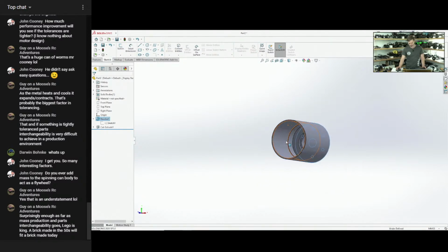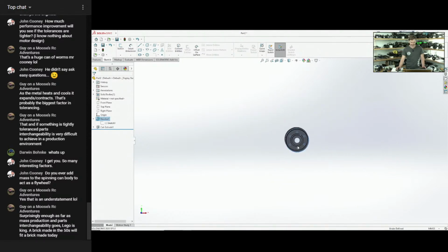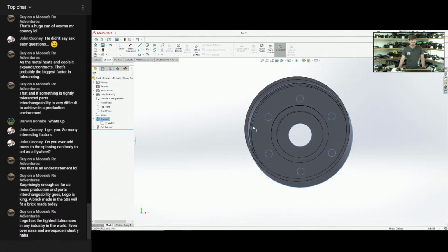So what we need to do is, it's a balancing of tolerances on so many levels. If the stator ends up sitting kind of crooked off to one side, like let's say we did just 5/1000ths of an inch tolerance on there, and it's like a hot dog in a hallway, then our stator, when we glue it in, is going to have the ability to kind of slip one way or another.